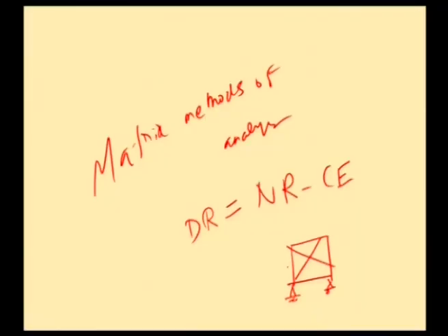If the external reactions or forces are able to be solved with the help of static equations of equilibrium, then we say the structure is externally determinate. And if we have excess reactions, as we have seen in the case of propped cantilever, continuous beams and fixed beams, then we say they are externally indeterminate. And in case of trusses like this, we will have additional internal forces.